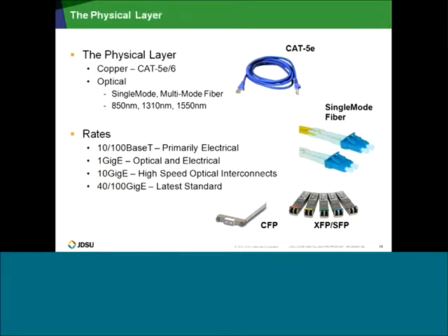Okay. So in terms of the physical layer, in order to transport Ethernet, there are several ways. For short distances, a Cat5e is just fine, with a maximum of around 100 meters. If you want to go longer distances, of course, optical cables are required. And in that case, you can use pluggable optics, and then